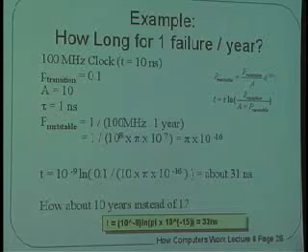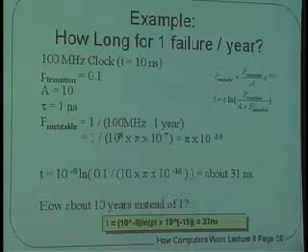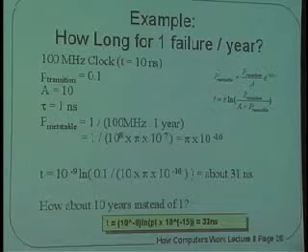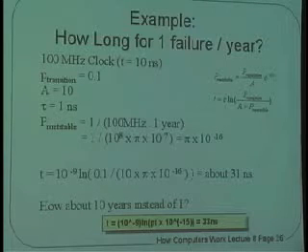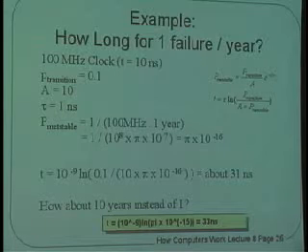And let's say that we decided that we wanted the chance that you're metastable to be such that even though it's doing 100 million arbitrations per second, I only want one of them to go bad every year. I'm willing for my system to freeze up once per year, because after all, it's running Windows and it freezes up once a day anyway, right? So once a year is a good number to use.